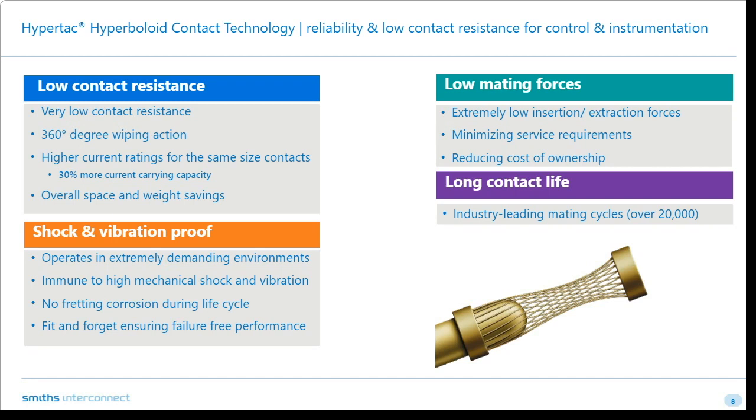Because particularly if you have an application where you require multiple mating and demating cycles, then in any other contact technology you would, knowingly or unknowingly, inadvertently set in that failure mechanism of fretting, or create force when you push the pin onto the socket, and that goes into the vicious cycle of increasing contact resistance, and starts the cycle of a good to a poor performing connector.